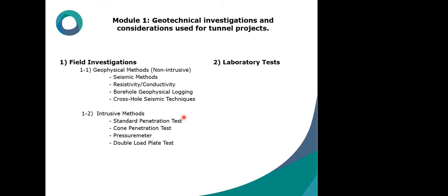For example, suppose facing high groundwater pressure in a tunnel project. Such kind of problems may suspend the project for months if the designer didn't have prior knowledge about that. On the other hand, if there is prior knowledge about it, the problem can be solved in many ways by changing the route or considering retaining or proper drainage at a proper place.